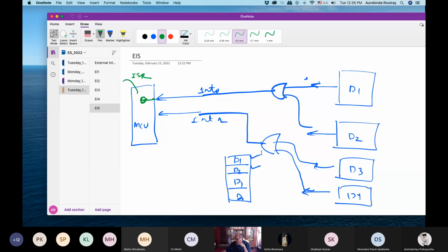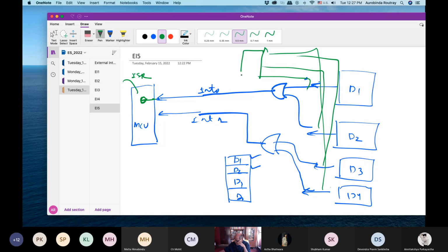No, you have to connect these also to the flag, some ports. 4 flags. So this will enable 4 flags. You read these flags through some ports. There is a port C, port B, port D. So you can use a port to read these flags. Whichever flag is enabled, that interrupt service subroutine you have to run. So this is called polling. You can figure out from that which one it is. So you please do that.